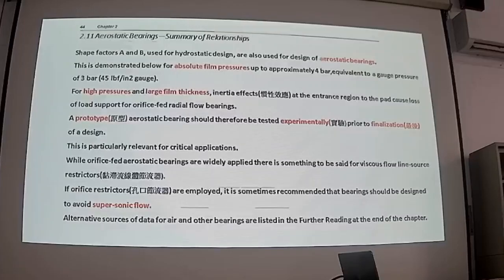The second reason is that for the air bearing, it is very difficult to heat up the bearing because the air is constantly exhausting to the atmosphere, so it carries away the heat. Okay? So the temperature rise in the bearing never happens. If you don't have a temperature rise in your bearing system, you don't need to consider using the